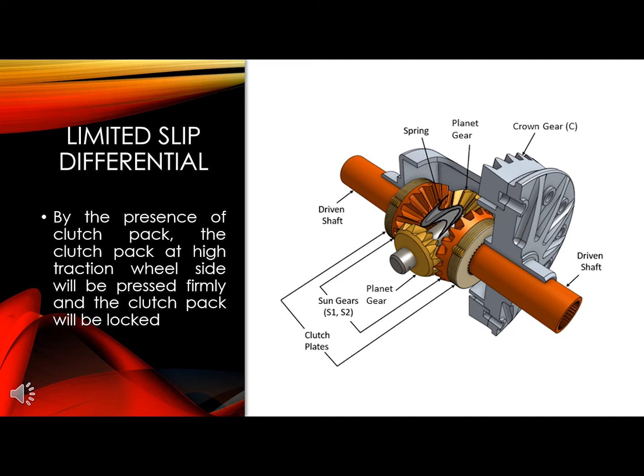The space between the side gears is fitted with a preload spring that always gives a thrust force and will press the clutch pack together. So there will be no gap between the gears and the clutch pack, so the response will be faster.